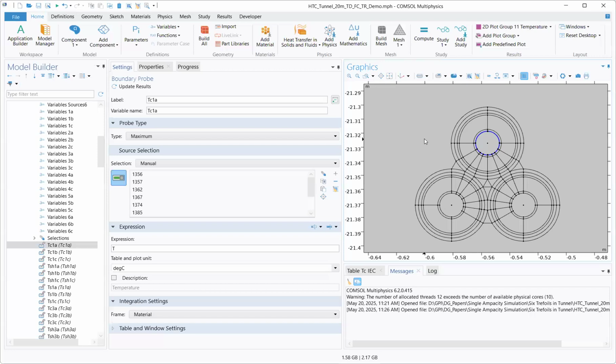I worked with ANSYS for like a year and a half. I already had experience with COMSOL going in, so I already knew what COMSOL could do, and I was asking them if ANSYS could do similar things. ANSYS Maxwell by itself does not have any probes to measure any quantities as the simulation is running. We cannot use the variables as I use them here. The only variables available in ANSYS Maxwell are basically parameters. They're not even real variables, just parameters.